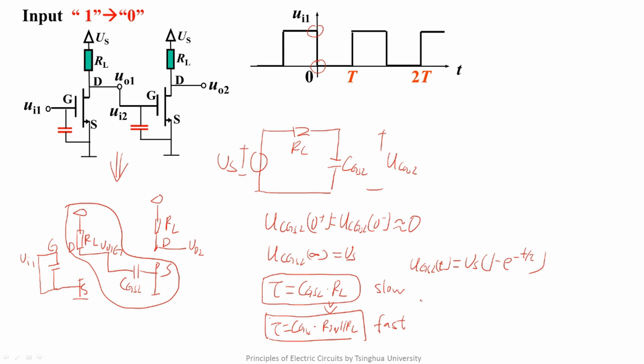Besides the parasitic capacitor CGS in MOSFET, because of the insulation between two parallel conducting lines, positive and negative charges accumulate on both sides respectively, and thus form the voltage difference and parasitic capacitor. According to the discussion in lecture 46, the value of the parasitic capacitor is inversely proportional to the distance between the two lines, which means the smaller the distance, the larger the parasitic capacitance is. This is a great challenge to microelectronics.